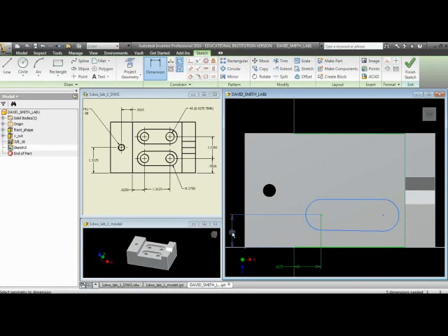Okay, next thing I'm going to do is put in some dimensions. Now I can dimension the center of this to the edge over here. That, it says, is 0.625. So I can locate the centers of these things from the edge here up to this point is 0.75. It's pretty close. Then if you want, you could, let's try this. It may already be done. Nope, it's not. So I'll go 0.75.